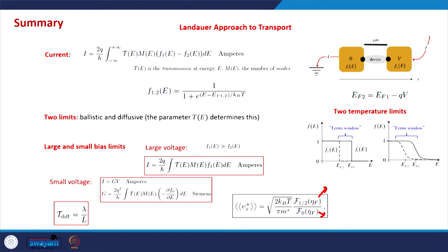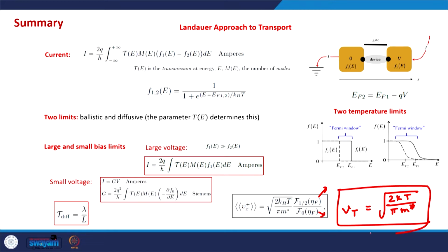and that is why we can cancel out the term in the numerator and the denominator, and that is why this thermal velocity, the unidirectional thermal velocity, is just defined as this thing without the Fermi-Dirac integrals, because this is the velocity at equilibrium, which means we are assuming that the below threshold conditions are prevailing, and below threshold conditions are quite similar to the non-degenerate case conditions.